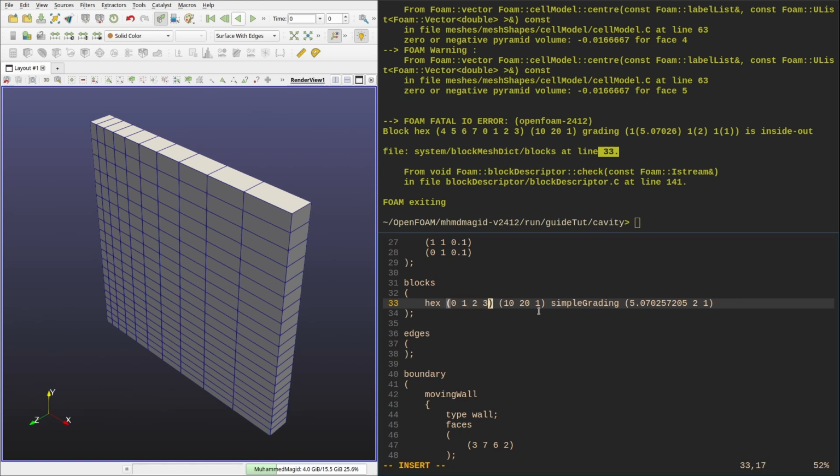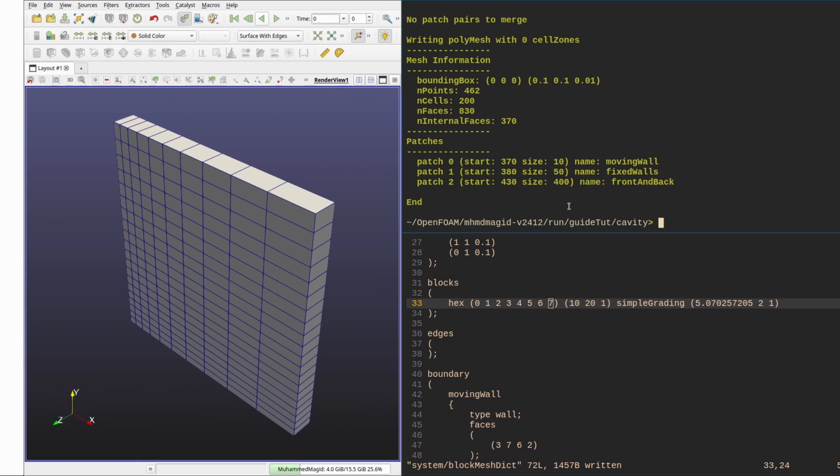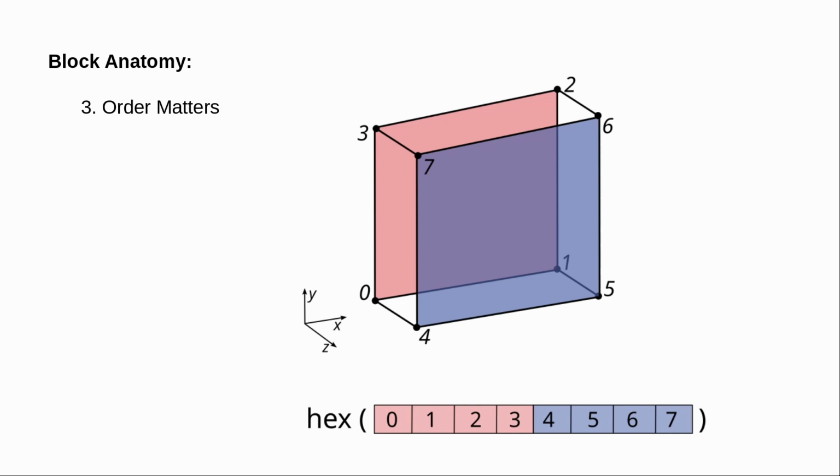You must start with the vertex that makes it look right-handed. In this example, the vertex 0 achieves this. So second step, after you specify the origin, you put your right hand on the 0 point, your thumb pointing to the Z direction, and the rest of the fingers rotate in the direction that defines the rest of the points. After you write the points of the back face, you write the projection of the points in the front face in the same order.